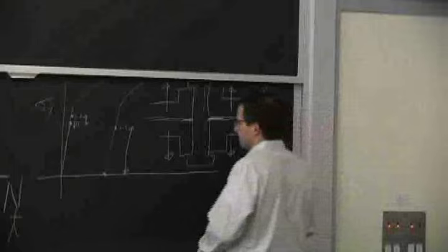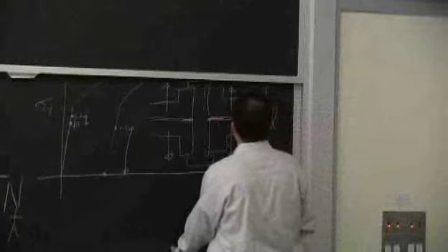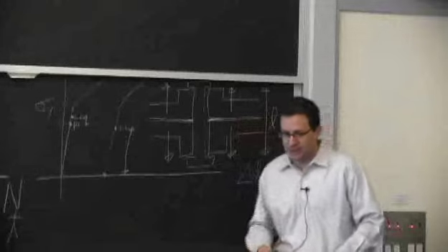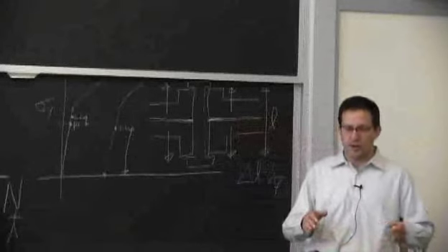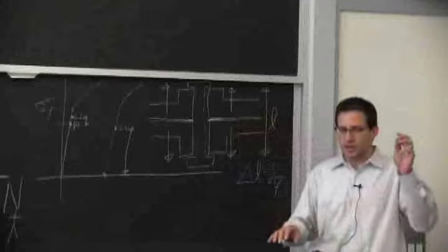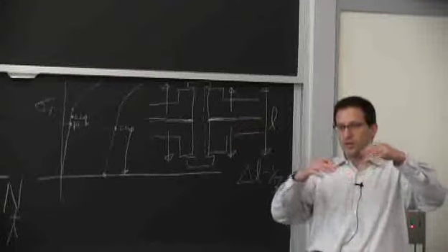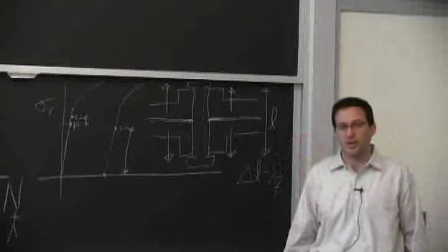The other concept was the Goodman diagram, and I don't think we have to restart it. It was this line where we look at the mean stress and the stress amplitude. If you're below the line, you're in the safe zone. If you're above, you're going to fail.